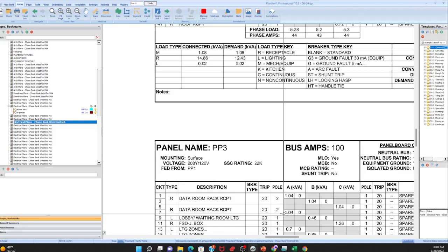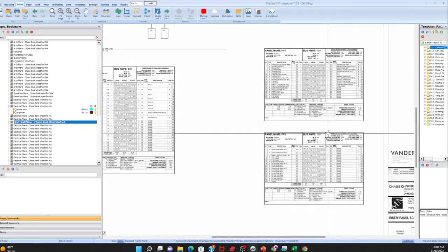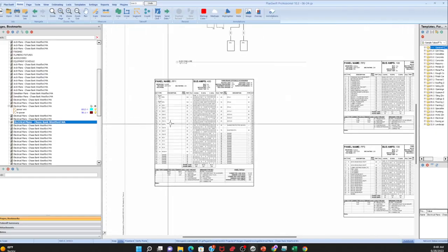If it doesn't tell you, you just need to make it known that it doesn't tell you. A lot of times your electrician who actually does the work will know, okay, make that 2 number 10s and 1 number 8, or the other way around, 2 number 8s and 1 number 10.